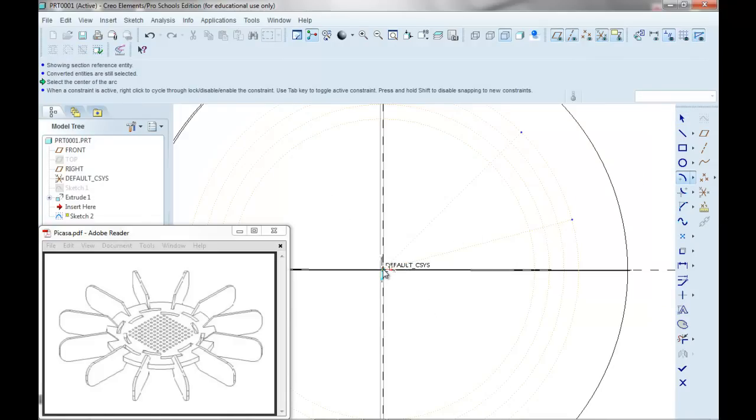I'll click on the center, and then come up here and select. Now I'm still in the command, so I'll come back and select the center again, selecting that intersection and this intersection. So that forms the two sides of my arc, and now I'll come in here with the line and select that piece and select that one. So that's my closed area for my first slot.